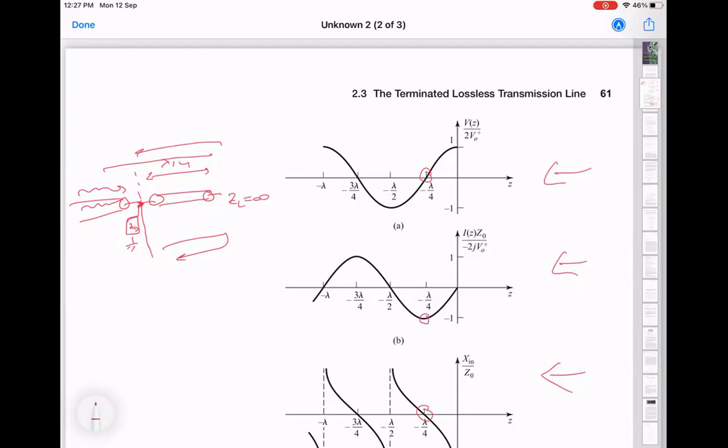The reason I mentioned this is that these ideas of looking at places where voltage is 0 have an equivalent: there are places where currents are 0. Right? So what will get unaffected there is something which is in series with the transmission line. If I go here, I see current is 0 at this point. So if I have lambda by 2 and I connect something between two transmission lines, the device is sort of here.